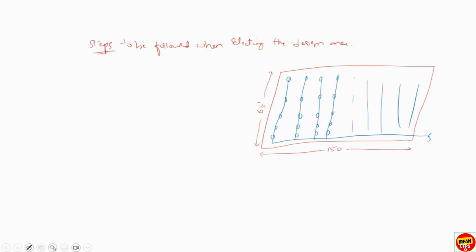Now I'll take some other color. This will be the S, 13 feet. You know already area is equal to S into L, right? Coverage area of the sprinkler will be S into L. So along the branch line, you consider as S always. Okay, just remember this point. And between the branch lines, we consider as L. So now, for example, I consider 13 feet as S and 10 feet as L.